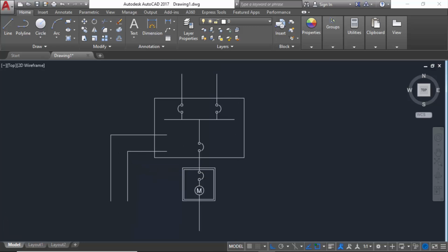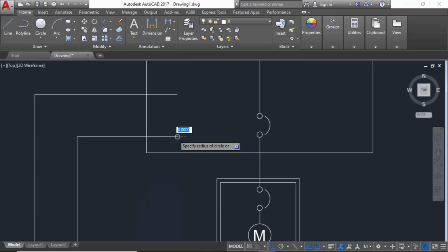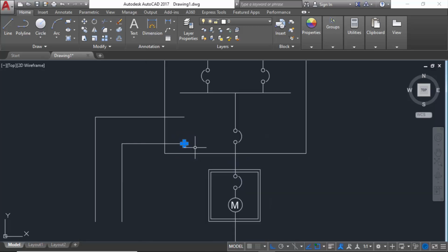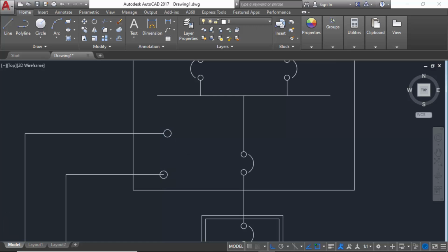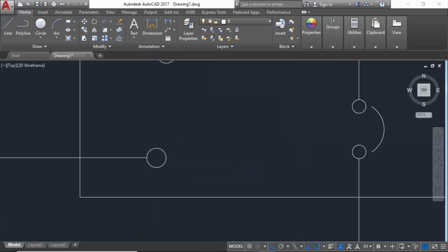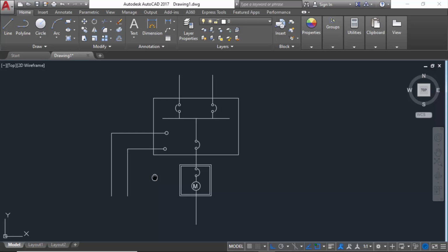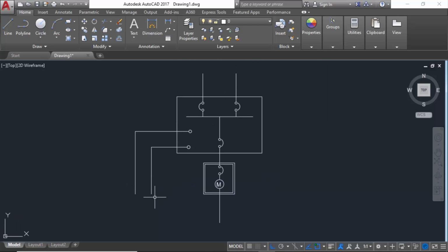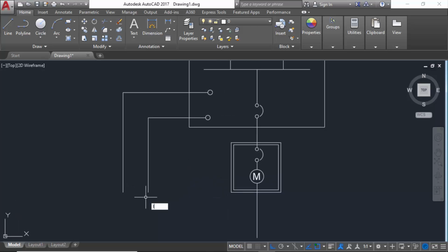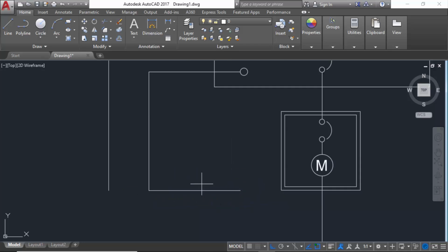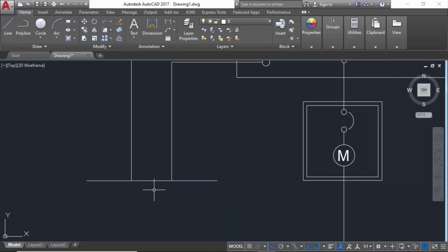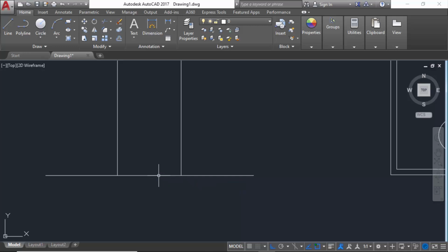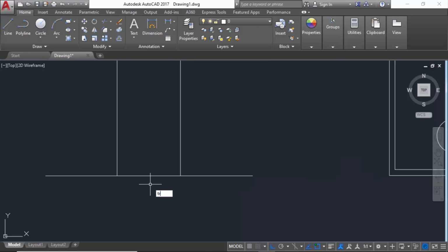If you are typically giving a three-phase supply to your house, you have to make the grounding and neutral grounding also, because it is very essential. You have heavy loads inside the MDB box. So in this single line diagram we are typically representing the three-phase supply. You can see that here you have to make the grounding symbol. We will create the grounding symbol here to represent the earthing.